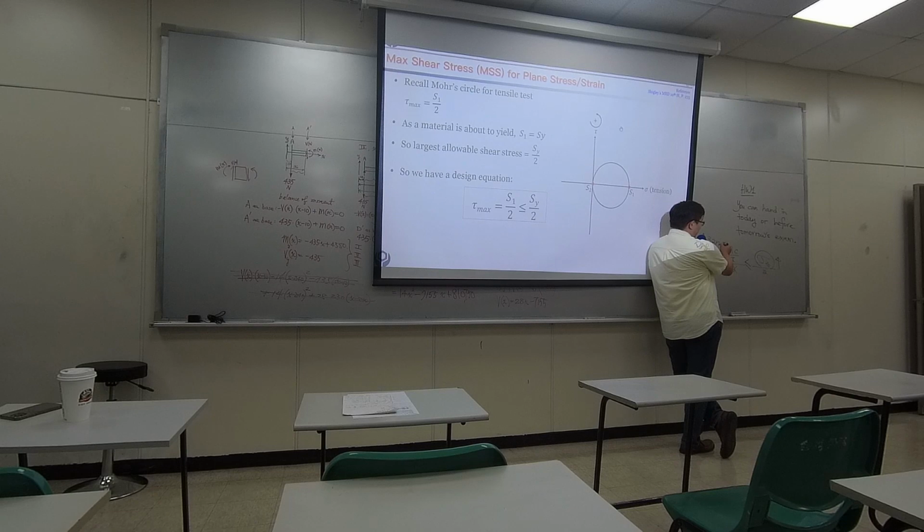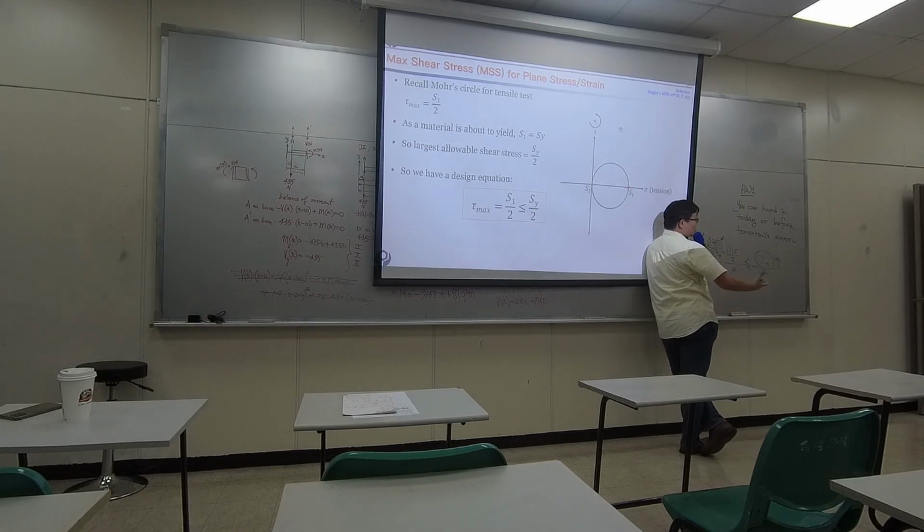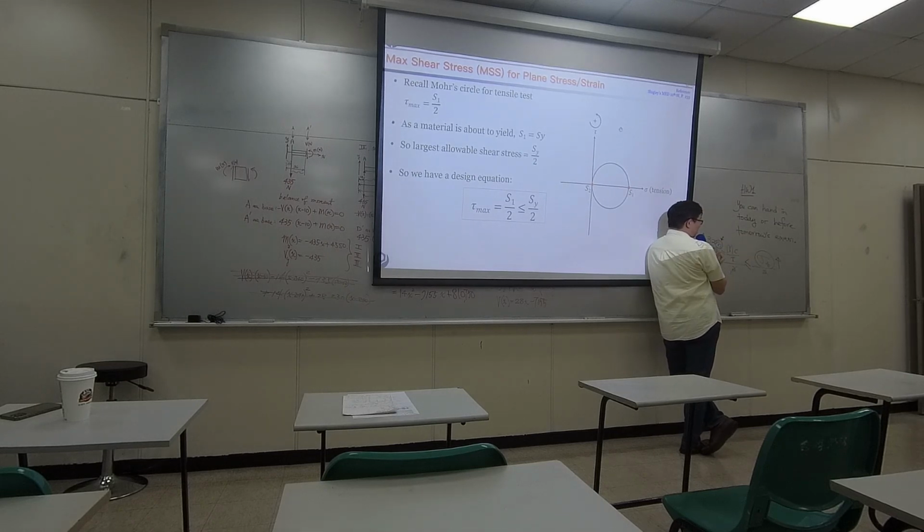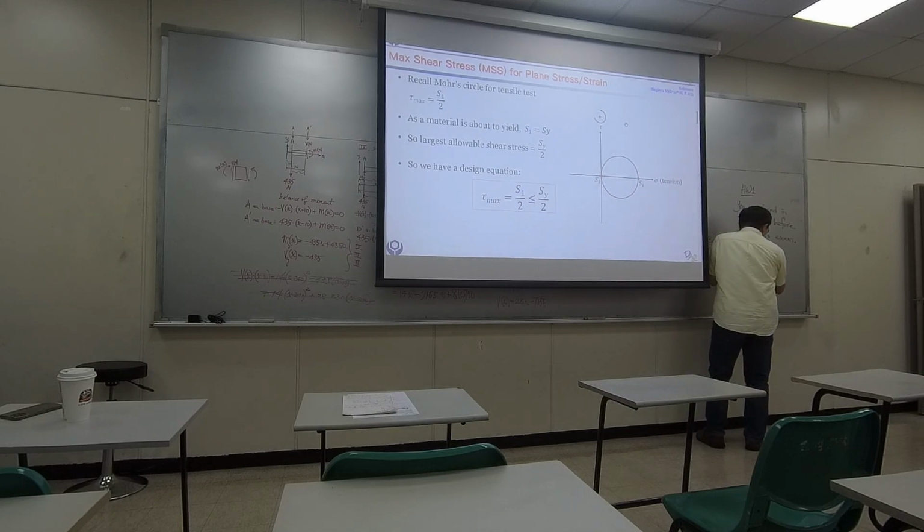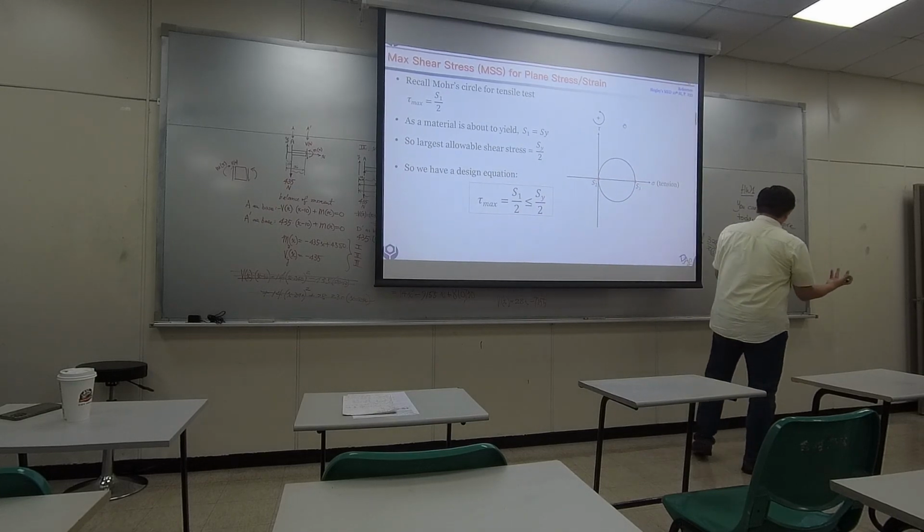Or what you can do is to carry lower loads. Why would you apply a greater load to the part? Just apply a smaller load, then you have lower stress. So in our design, there are 3 options already. You can change your material to make the part stronger.